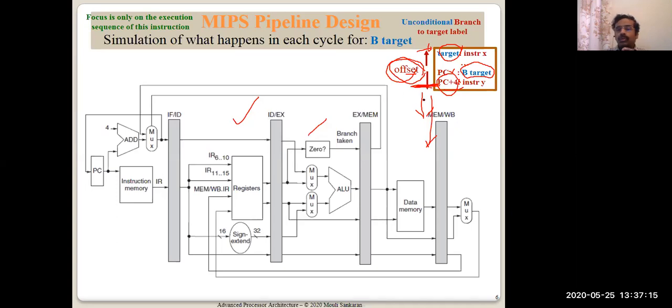If you do relative addressing in the jump, then it is possible, because you can use the existing PC value and add or subtract some value to that and get the target address. So you are trying to build a 32-bit address of the target instruction from a 16-bit value, which is an offset.